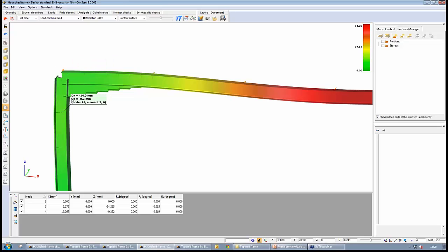inside of this shear box, and the peak bending moment in the beam and the peak bending moment in the column also is calculated at this node. And usually this area and this node, these cross sections here are the dominant cross sections of our frame model.